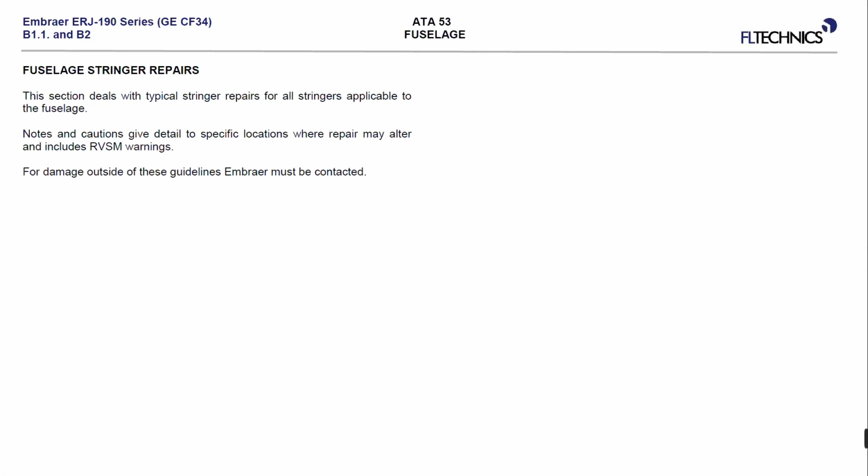This is the separation between the airplanes. The zones which are near to the air data probes always have to be smooth and clean to provide proper air data inputs, and also this will increase the reliability of the air data system, which will keep the aircraft flying on a specific flight level. So in this case, the airplanes can fly in a reduced separation.